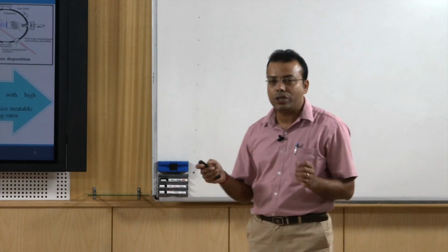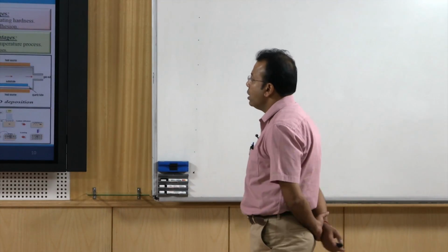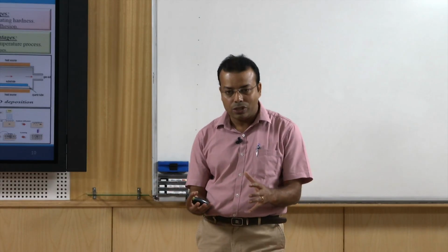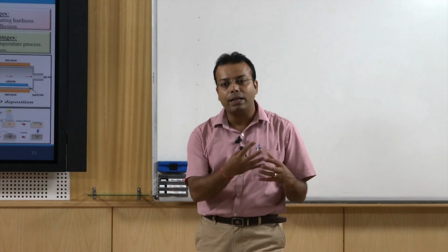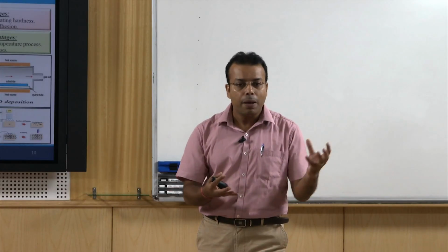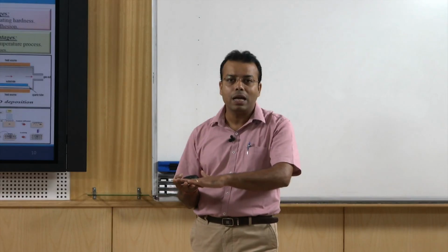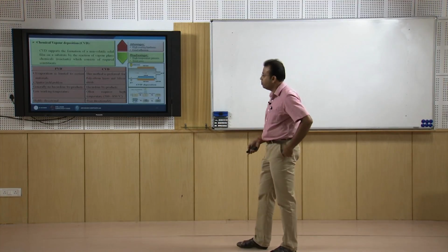So, that is in general called the physical vapor deposition techniques. Next, the chemical vapor deposition techniques we have also discussed in our earlier slides. The chemical vapor deposition is the same thing, where we are introducing some kind of molecules, ions, or plasmas, but those materials can react with the substrates, form a new species, and in this way do the coatings onto the substrate material.